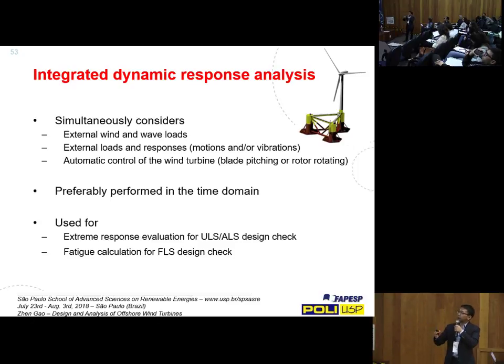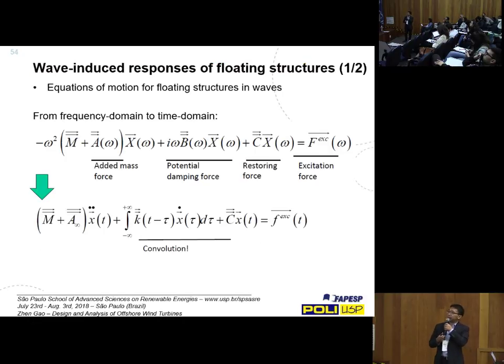And if you have a model and method ready, then you can do this for different types of wind and wave conditions, and then you predict extreme and fatigue loads and load effects. So that is important. Another point I want to mention is that most of the hydrodynamic loads, they predict using frequency domain method. That is predicting the loads on the structure in regular wave condition for a given omega. And this is possible to convert into the time domain.